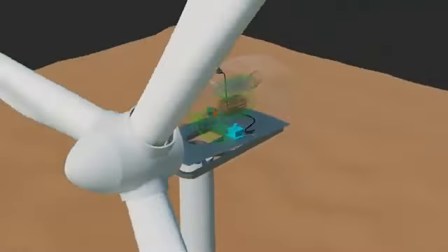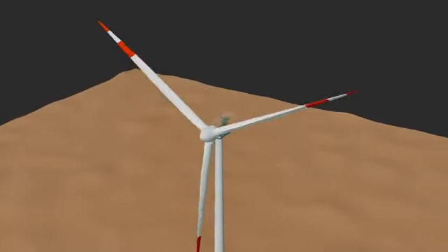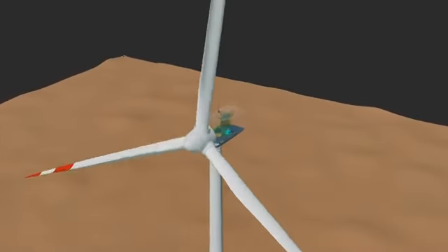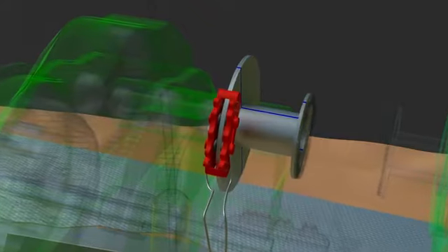When wind speed reaches cutout speed, the blades are first slowly feathered to 90 degrees, bringing the rotor to a stop aerodynamically. Only after the rotor speed is sufficiently reduced are the mechanical disc brakes applied to hold the rotor stationary. The brakes are also used for emergency shutdowns such as pitch system failure, grid disconnection, or component overheating and during maintenance operations. The brake system is fail-safe. Springs apply braking force by default, and hydraulic pressure is required to release the brakes.